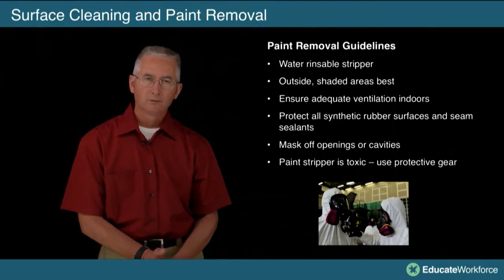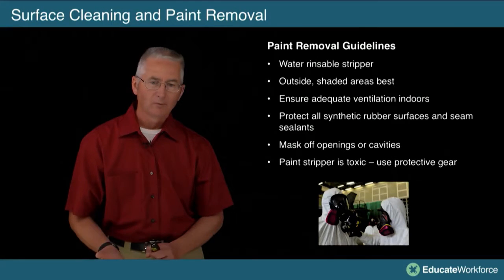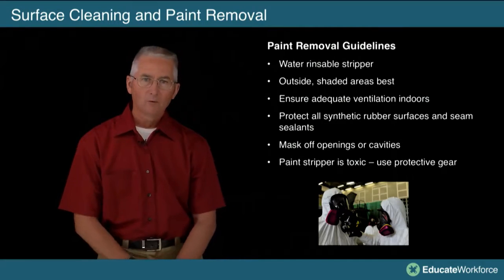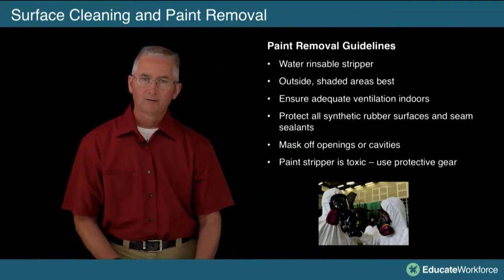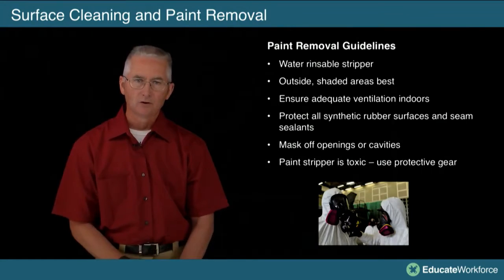A water rinsable stripper, you want something so that when you're done, you can rinse it off. And oh, by the way, we're going to try to do this outside. We don't want to do it outside at 110 degrees in the sunshine because your paint stripper is going to dry before it has a chance to do its work.